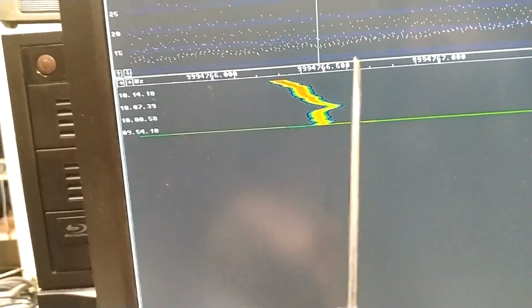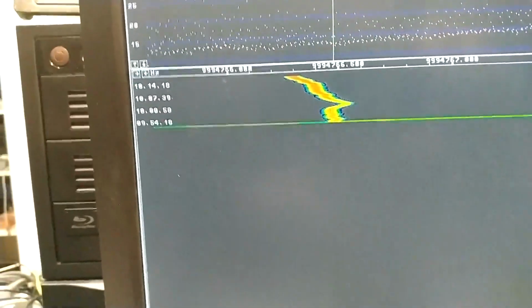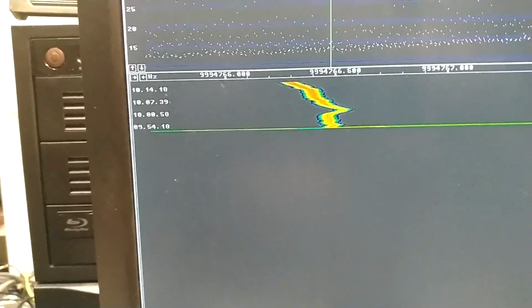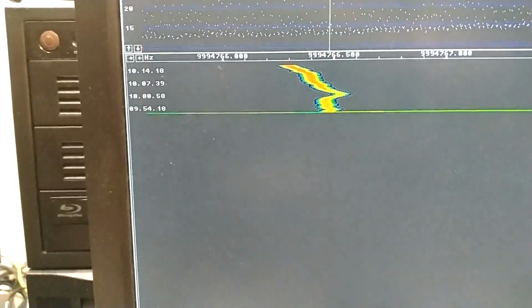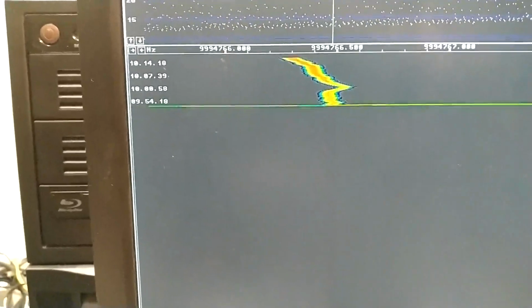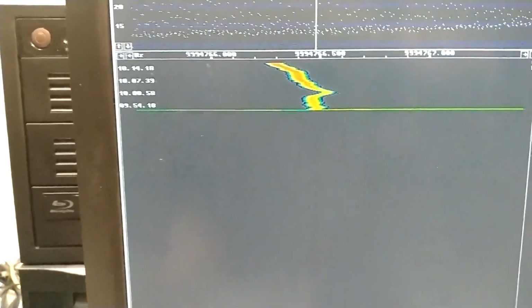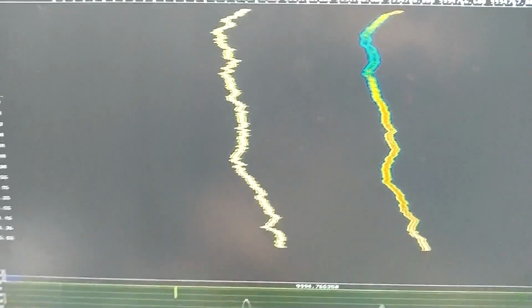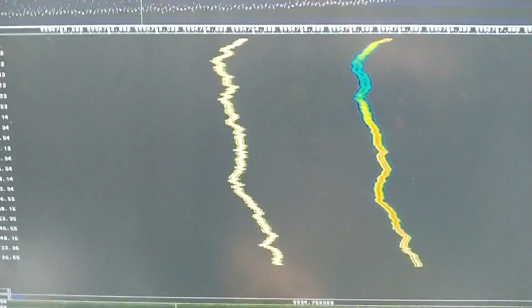One division here, 0.1 Hertz, corresponds to 1 millihertz on the fundamental, or 1 millihertz at 10 megahertz. I have disconnected the PLL. This means that I see the frequency difference between oscillator number 2 in the receiver and oscillator number 1 in the receiver.